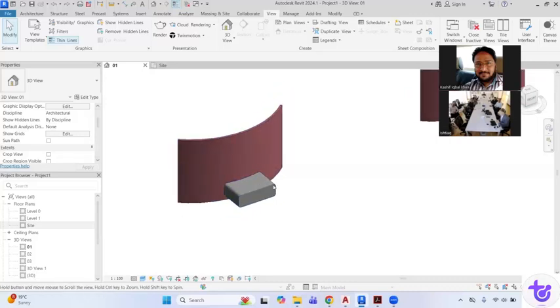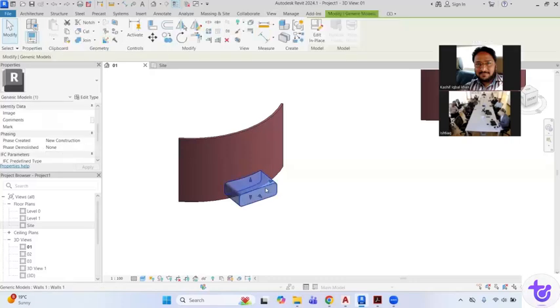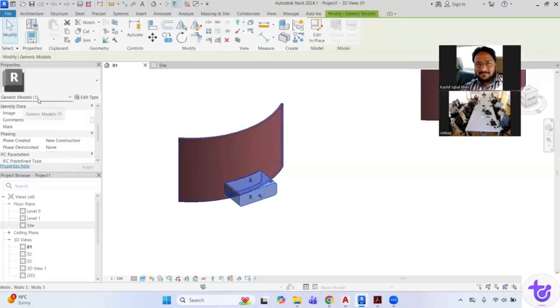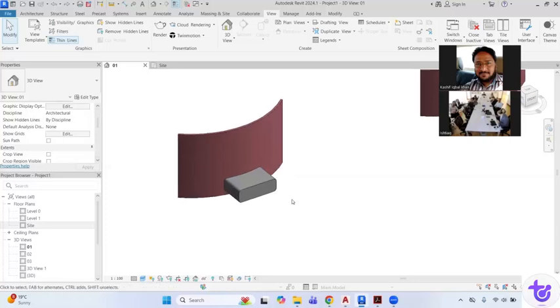Okay. So if, for example, this is not going to be a workshared file, you don't want to control the visibility with the help of the workset, but still you want to control. And if this has the category generic model, you cannot turn it off. Either you can turn it off with the help of a filter, or there's another way: you can create a subcategory.